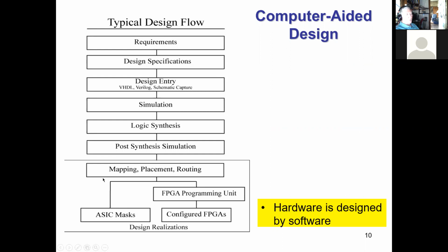And there are probably a few other steps in there, like seeing how many we can fit on a given wafer, and figuring out what kind of bonding wires we're going to use and how they're going to package them. And there may be several different package choices. In some cases, we may not bring out all the pins. In other cases, we may bring out all the pins, or even things that we might not bring out on other packages. Okay, so these steps all require lots of verification.